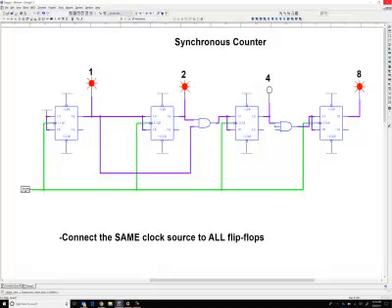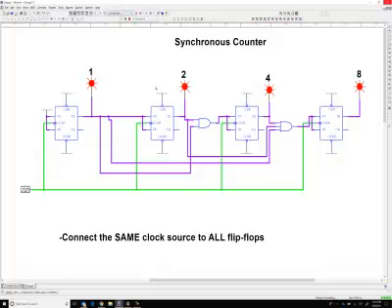There's a different way, let me show you. So it's this first one, then I'm going to check the twos place, and I'm also going to check that the ones place is on. So I check all 3 for this last one. And it's going to work, you can see, watch. When this one is on, the twos toggles. When the first 2, the fours toggles. And then when these are all on, now the eights toggles. And it's working, counting forward properly.